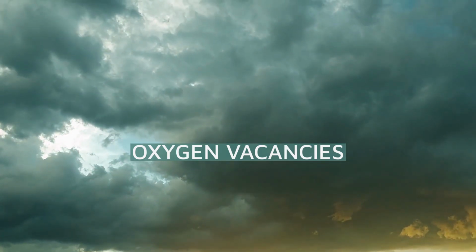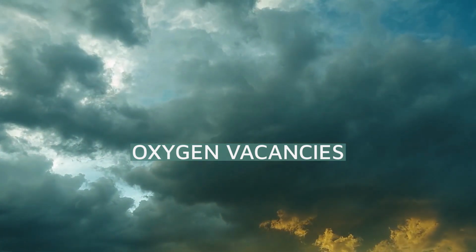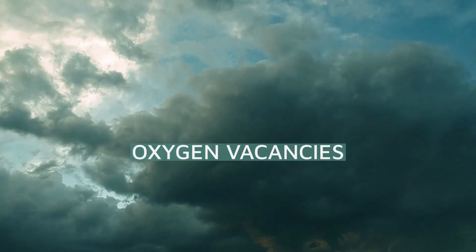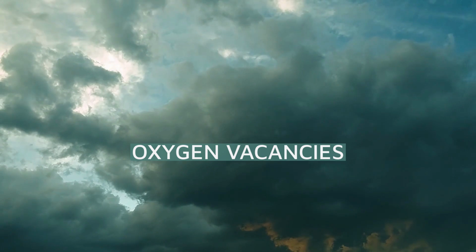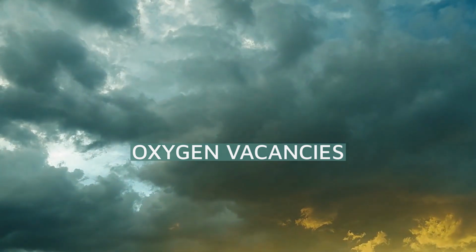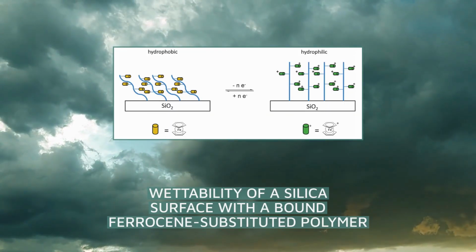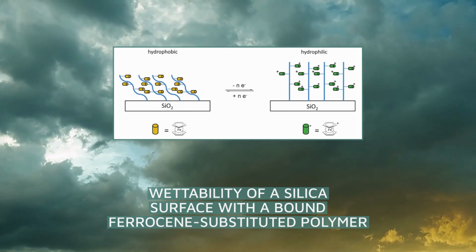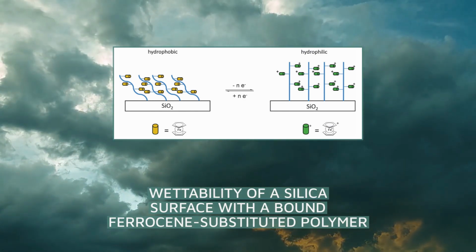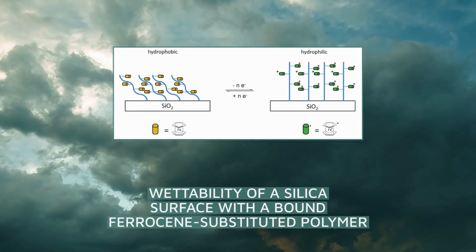Oxygen vacancies. Rare earth oxides exhibit intrinsic hydrophobicity, and hence can be used in thermally stable heat exchangers and other applications involving high-temperature hydrophobicity. The presence of oxygen vacancies at surfaces of CeO2 or other rare earth oxides is instrumental in governing surface wettability. Adsorption of water at oxide surfaces can occur as molecular adsorption, in which H2O molecules remain intact at the terminated surface, or as dissociative adsorption, in which OH and H are adsorbed separately at solid surfaces.